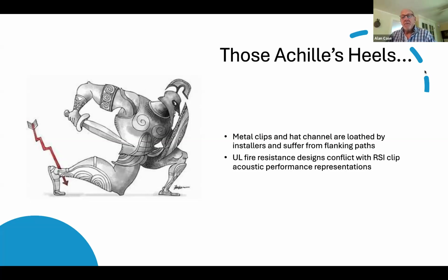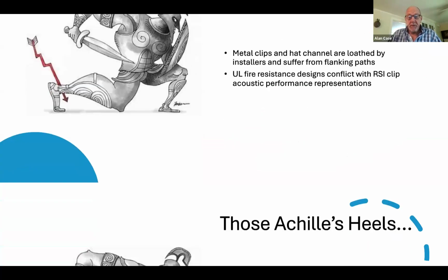Composite gypsum panels. You've all seen that stuff. Some of them weigh 300 pounds. I mean, it's incredible what they have out there. But they're primarily designed for walls. You can't use them in the ceiling. They're ineffective, and they certainly can't be attached to any metal product. They're too heavy, and then the screw problem with the overloading fasteners creates deflection, and so the manufacturer tells you you can't do it. So there's no escape for the noise there.